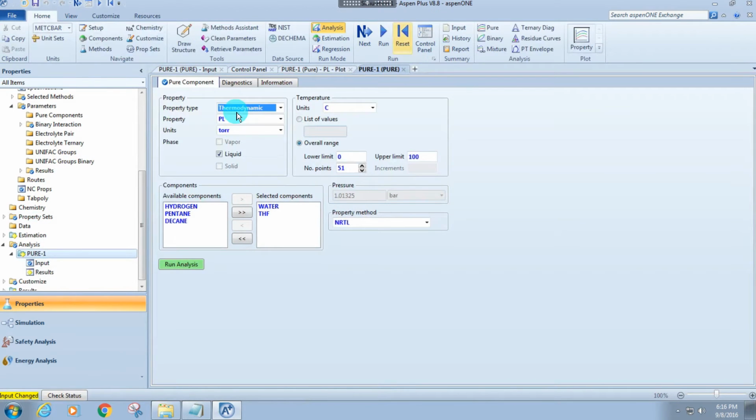So this pure investigation here makes Googling almost useless. Whether you want to see how density relates as a function of temperature or any property that you would like, you don't have to Google for tables anymore. You can use ASPEN to generate every parameter that you can think of. In this case, for our project specifically, vapor pressure is useful because it provides a basis of the relative volatilities of the components. It gives you a basis of where to split first and how to design your sequence of distillation. Okay.